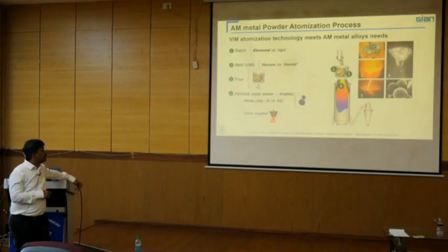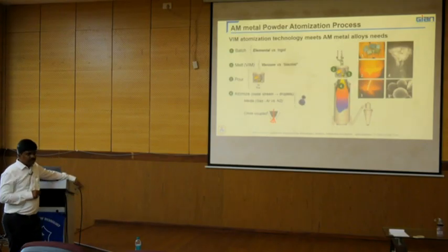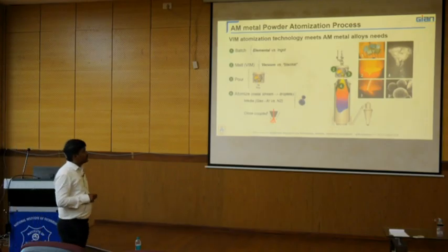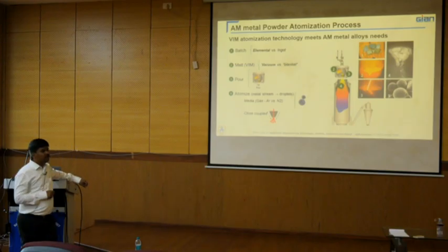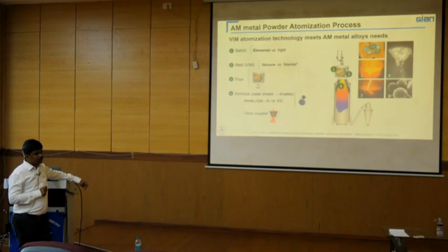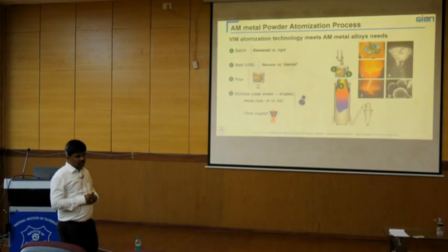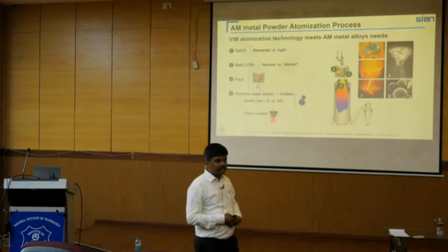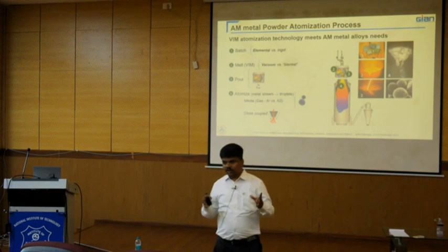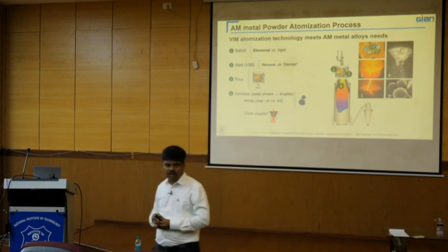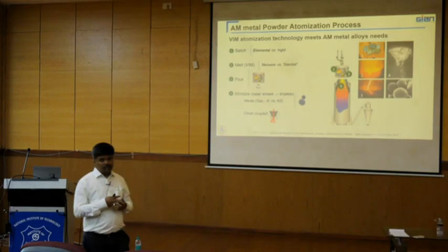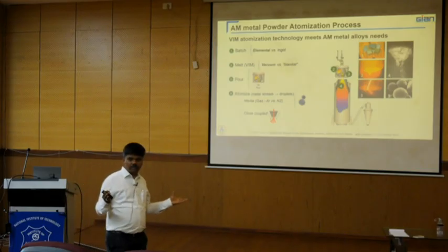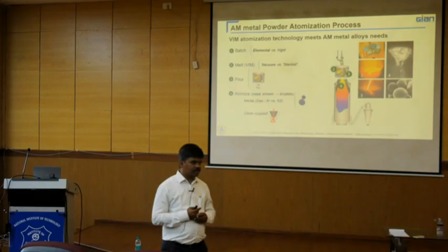And if you see the recent developments by 6K Additive Solutions, that is the vacuum induction atomization technology that is especially suited for titanium powder manufacturing. Because with titanium we generally use argon, as titanium is a highly oxidizing material, it will quickly create titanium oxides. To protect against this oxidation, we have to use either a vacuum chamber or an argon atmosphere, right.